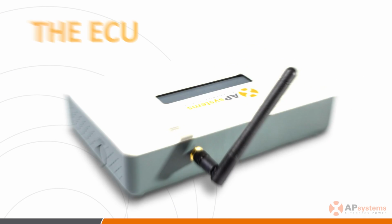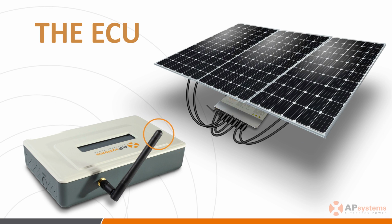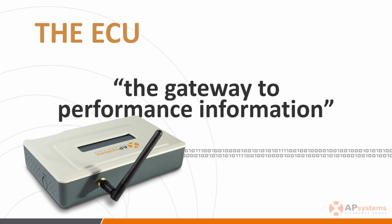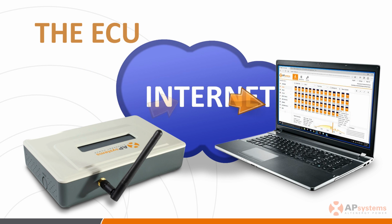A few quick words about installing the ECU before finishing this training module. As mentioned earlier, the ECU collects and stores the performance data from each of the microinverters using the Zigbee protocol and sends it to the APsystems database via an internet connection so that the array can be monitored online. The ECU, while optional, is an essential component of the remote monitoring system that should be thought of as the gateway to the performance information that can be retrieved from each inverter and its assigned PV modules.